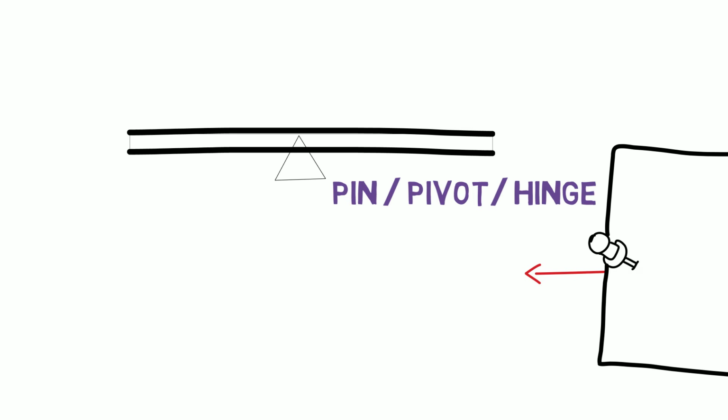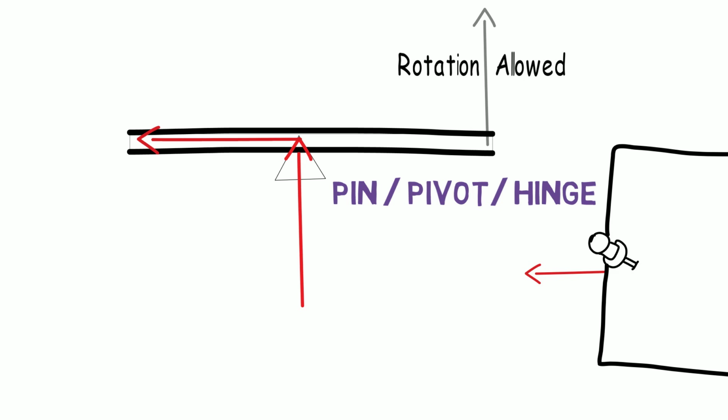Similarly, a seesaw, where the plank can be considered as a beam. The support would not allow the plank to move in a linear direction, but if you apply some force at a distance from the pivot, a moment will be produced. Therefore, when a pivot joint is used, the only restriction it causes is for the linear motion, both along horizontal and vertical directions, but allows rotation motion. Hence, a pivot support has a horizontal and a vertical reaction force.